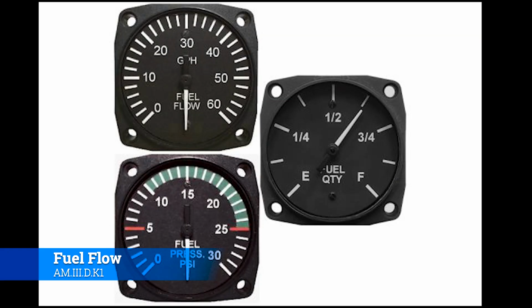First off is fuel flow. So let's talk about what fuel flow is, why it is important, and how we, as mechanics sitting there in the cockpit, can read the fuel flow to make a decision on if that's good or bad. All right, so on reciprocating engines, a lot of times you won't see fuel flow, you'll see fuel pressure, and that basically serves the same purpose. It will tell you, hey, look, this is the fuel pressure in the line.